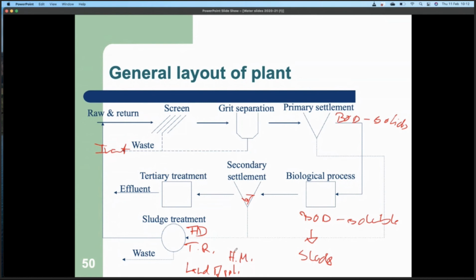And you can do fairly simple calculations, and there are maps available that tell you how long sewage sludge can be applied to land so that you use the benefits of it. So you say, how much nitrogen does my plant growth need? How much organic biomass do I need? And you apply the sludge accordingly.